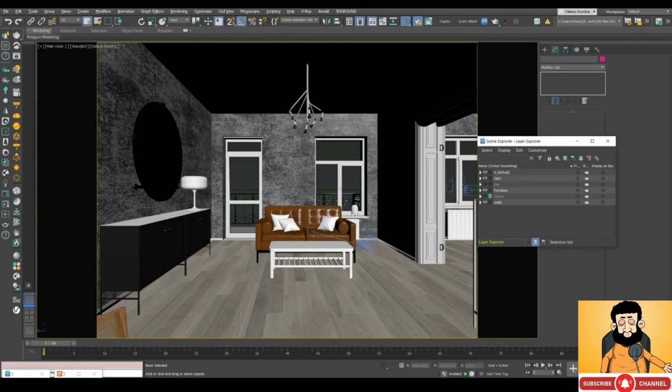All right. So we have curtains in our scene. We need to hide them in a layer and then set up beautiful lighting. And then we can bring back the curtains and do lighting correction. Because it's not uncommon that beginning visualizers leave curtains, and the curtains are blocking the light from the window. And visualizers then wonder why they can't set up proper lighting. So before setting up lighting, make sure nothing is stopping the exterior light from getting inside the interior.